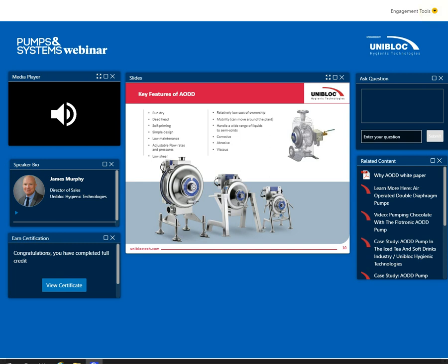Let's talk about some other features here. So the pumps can handle some semi-solids. As I mentioned earlier, there's two major designs in terms of the valves. You've got ball checks or you've got flapper checks. Ball checks can generally handle 1/4 inch, maybe 3/4 inch solids, depending on the size of the pump. Whereas a flapper check, the largest I've seen is about a 3.8 inch solid.